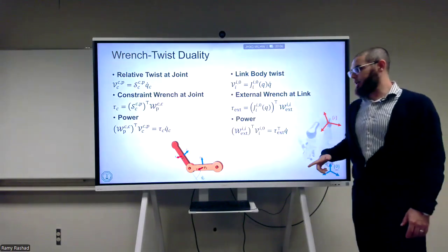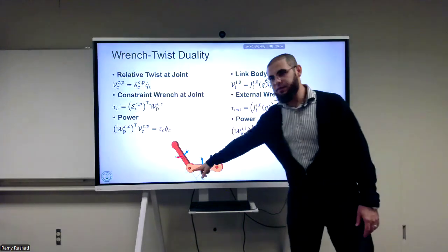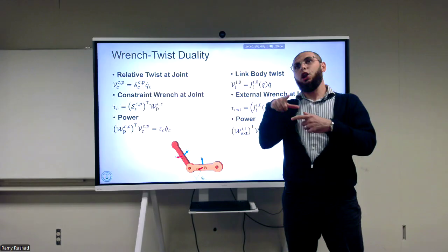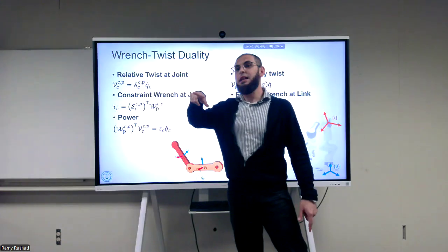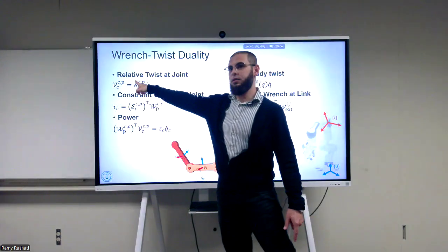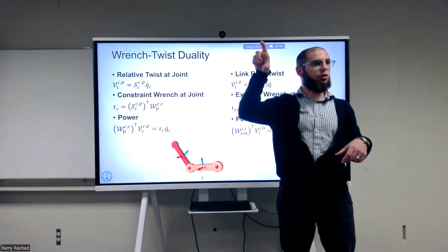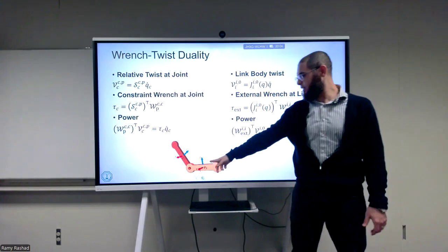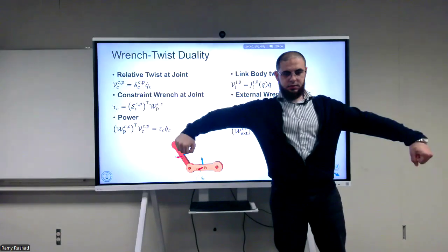The motor is actually something at the joint level, it's only along the screw axis, because the screw axis is exactly the motion you're allowed to do. You remember this is an S, right? It's 6 numbers. A lot of them were zeros. The places where it is zero means the joint is actually preventing both bodies from moving relative to each other. Intuitively, it's this picture. For example, take these two bodies. Am I allowed to move the two bodies like this? Why?